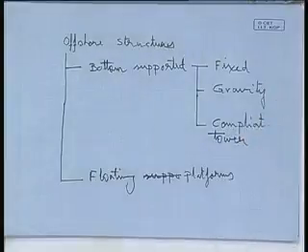So, fixed platforms, by the name only, generally have a so called substructure and a platform. Substructure means the structure below the water. The platform can be the simplest ones with one or two decks, or the more complicated, integrated ones with several decks with all kinds of drilling and exploration machineries, because it will depend on what purpose this offshore structure is being used.